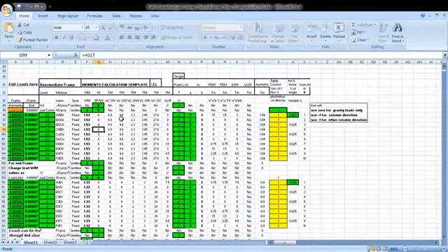Now this is basic information. We have load here, and we have span here. So we can say there are different types of moments. WL square over 8, that's one formula. WL square over 12 is another formula. WL square over 24 is one more. WL square over 16 is another. WL square over 2, WL over 4. Different types of formula. This is called UDL, meaning uniformly distributed load. The moment calculation template is for UDL, and this is a different one, WL over 4, and this is something like a point load.